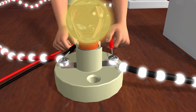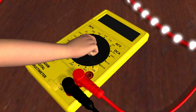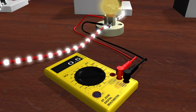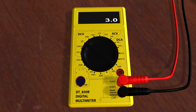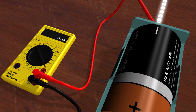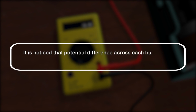Measure the potential difference across each bulb using a multimeter and record the observations as potential difference across bulb 1, V1, is equal to 3.0 volts. Potential difference across bulb 2, V2, is equal to 3.0 volts. Potential difference across bulb 3, V3, is equal to 3.0 volts. Potential difference across the battery, B, is equal to 3.0 volts. It is noticed that the potential difference across each bulb is the same as that across the battery.